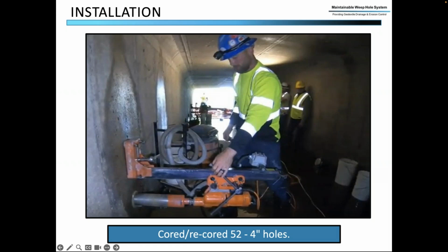The soil filtration component had failed. They lost a lot of backfill. They had to come in and repair a bunch of voids and sinkholes. Then they plugged all the weep holes. Well, of course, then over the years, pressure built up and caused cracks. They were losing soil fines. So the project was then to go through and restore drainage to this 172-foot box culvert, double twin barrel.